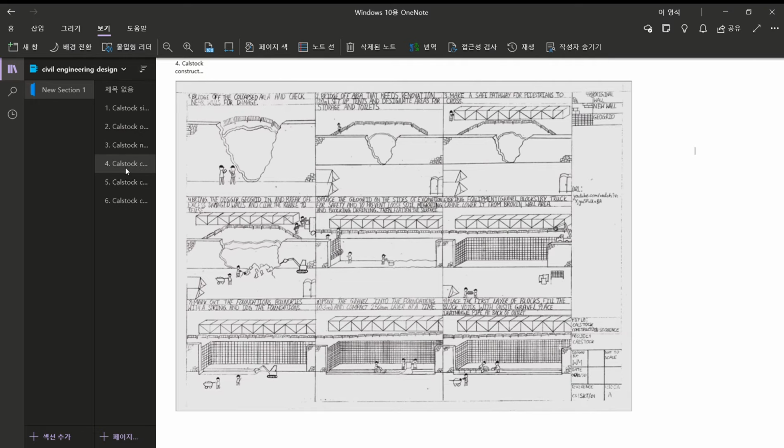Meanwhile, the geogrid will be transported to the area and workers will unload it from the truck. The workers will place the geogrid on the 3 sides of the excavated area by rolling it out from the top of the road down to the bottom of the excavation. The geogrid is used to hold loose soil back so it doesn't fall into the excavated area and block the draining. Then the surface of the excavated area will be flattened with a compactor.